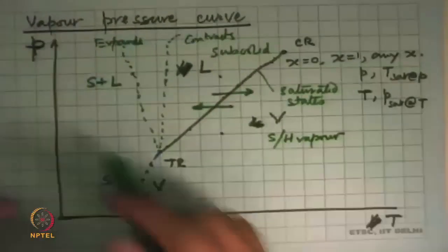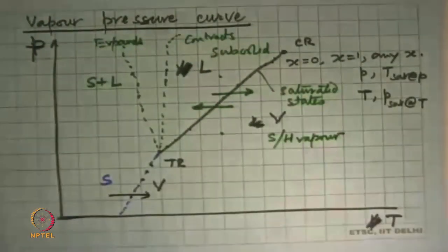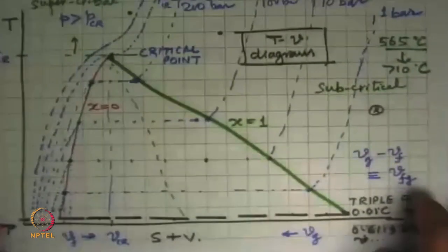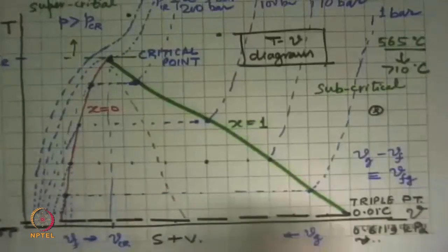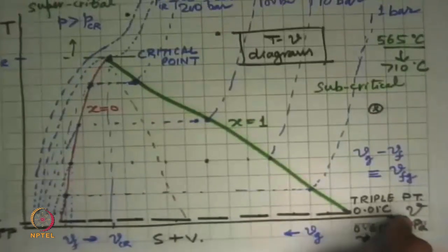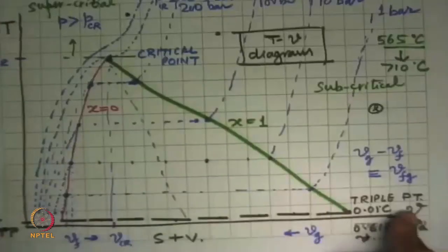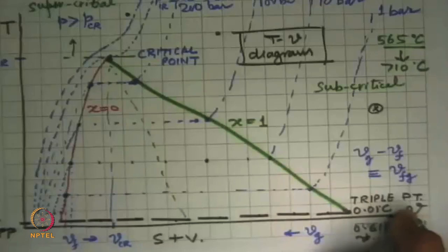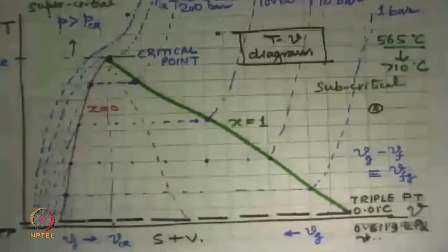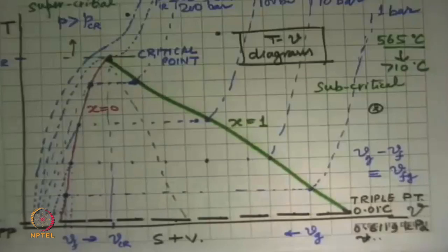So now we have a complete handle on liquid, vapor, saturated states. We now need to look at how we can construct a bigger picture out of this. For instance, if we take this picture and say, look, now instead of making it on two axes on a piece of paper, I will make T, V, and a third axis normal to the paper, which is P. So you have an XYZ system, and every state point can be located uniquely in that state.